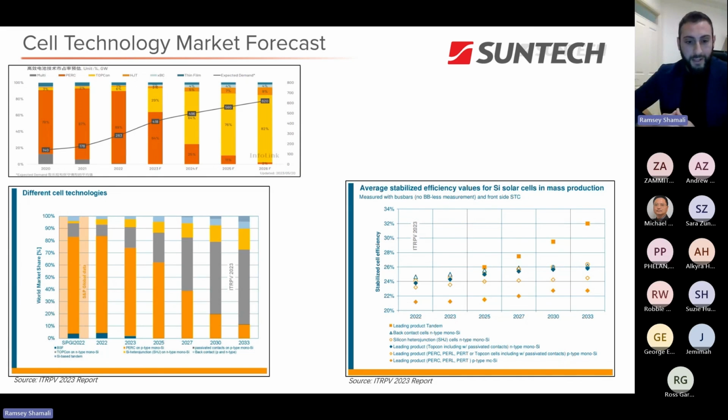It's a very good question, and I'm not sure if I have all the answers, but in terms of the new quality control and quality assurance testing requirements, I don't think there have been any additions in terms of different types of tests. They all stem from the IEC standard test requirements that you see in some of the slides, like thermal cycling, PID, LID testing, mechanical dynamic loading, all these things.